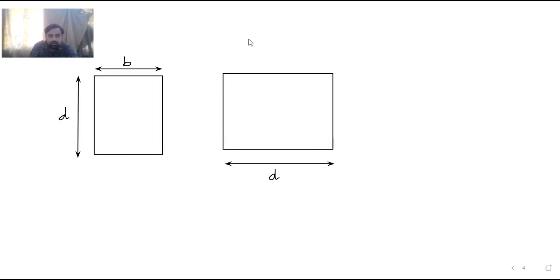Now the anchor plate is there. I can apply the pre-stressing force directly on this cross section, and then the stress is load divided by the cross-sectional area, which we can easily calculate.